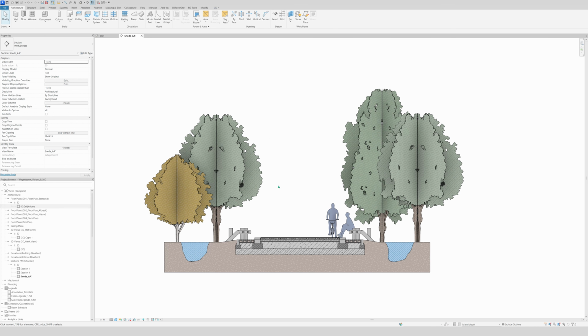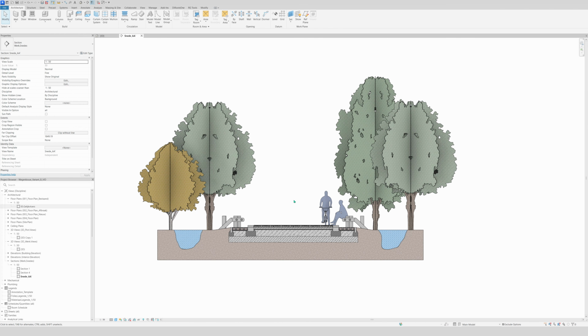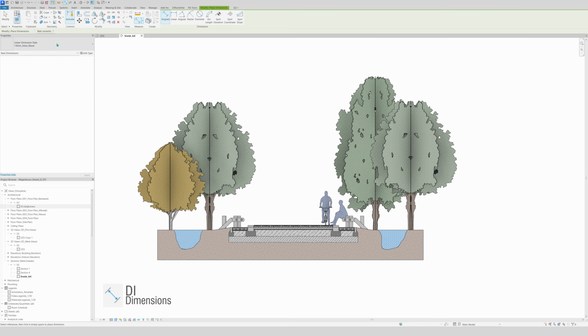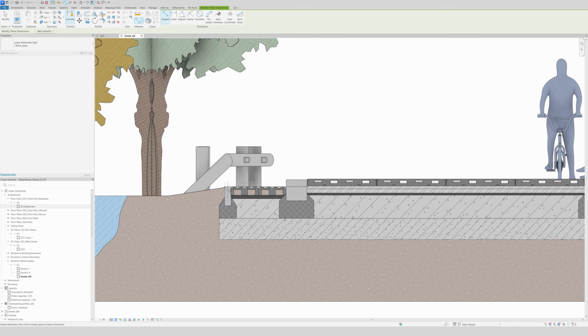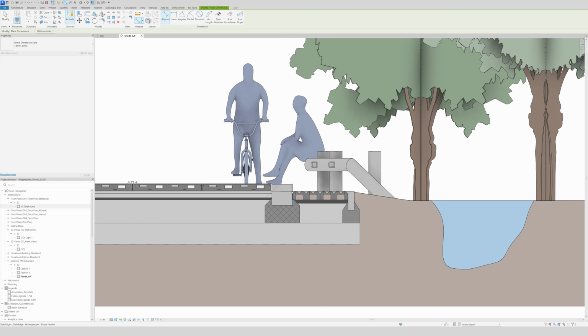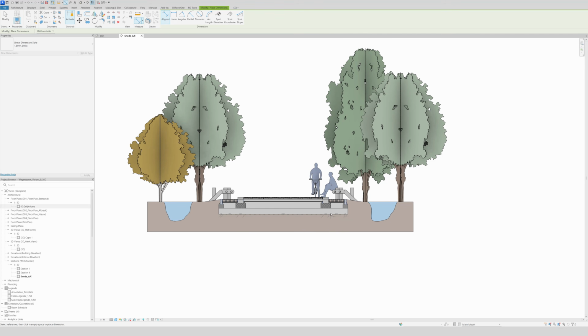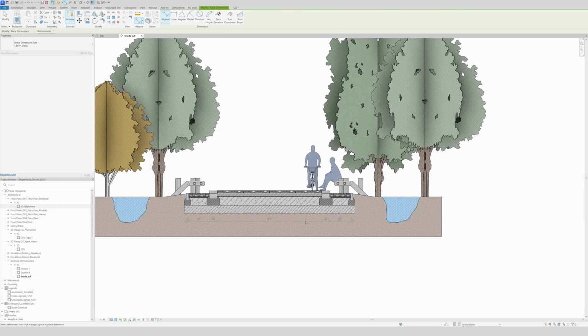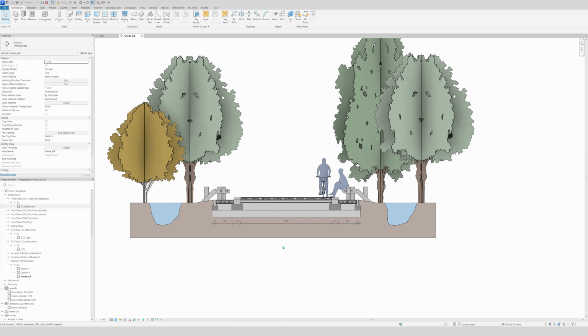The first thing that I will do is annotate the roads, how big they are. I'm going to use the shortcut DI for dimensions, and I will select the right one that I want. And now I will do the roads, like you see here. You will see in a minute why I do that. It's to make an overview of where everything is placed. So we will place it right here. Seems fine. And then we're going to name every road.